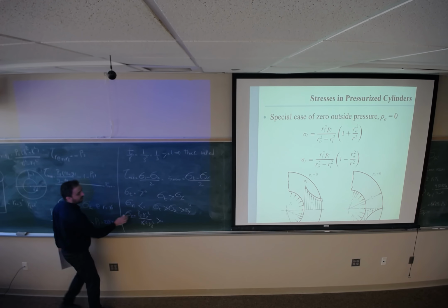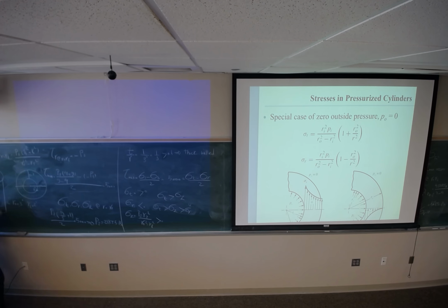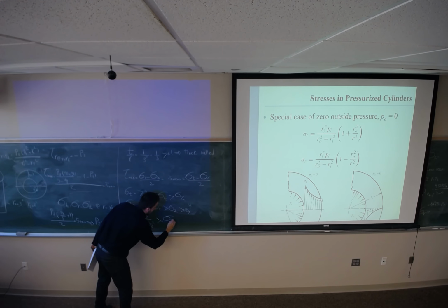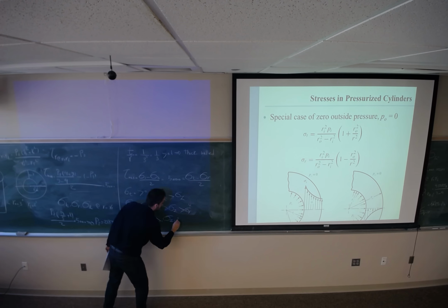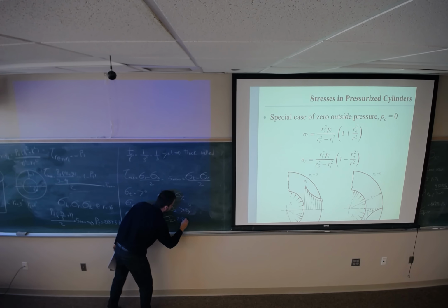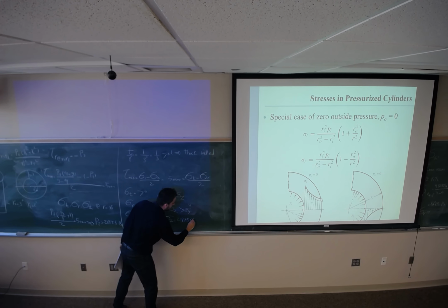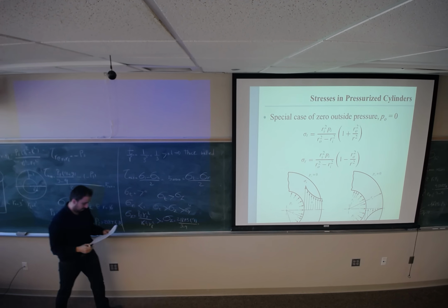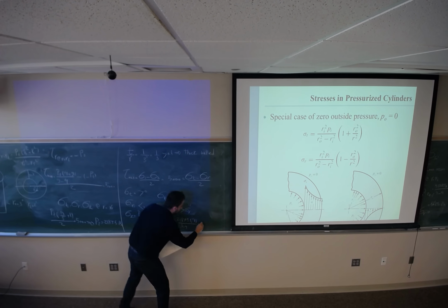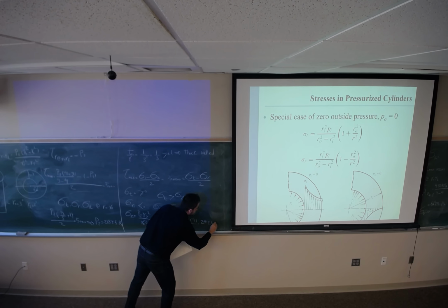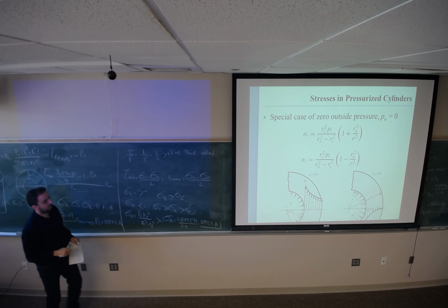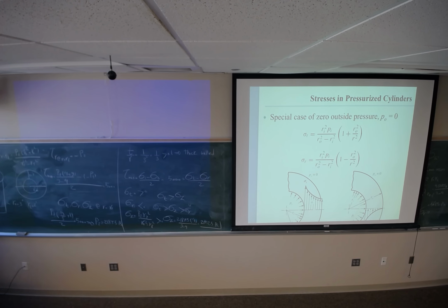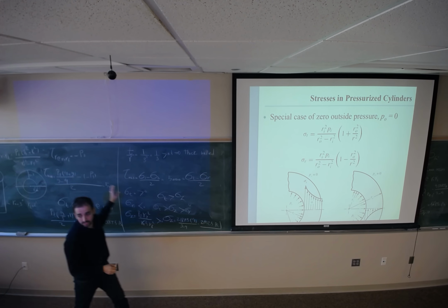since we have closed ends, we should find sigma_Z as well. 87.5, R_i is 2, R_i squared divided by 9 minus 4. That gives 2812.5 psi. So those are the 3 terms of the stress for this cylinder at the outer radius.